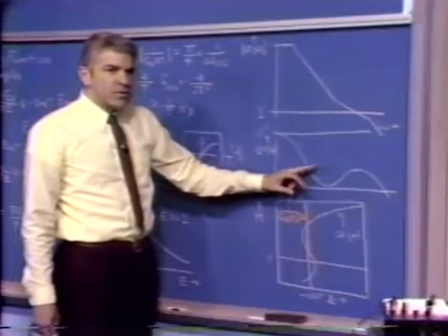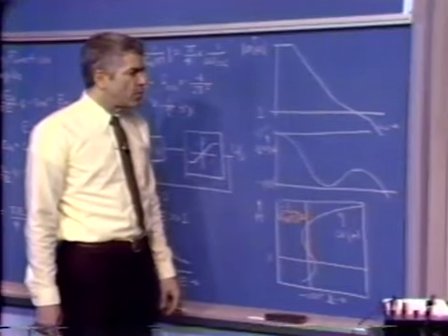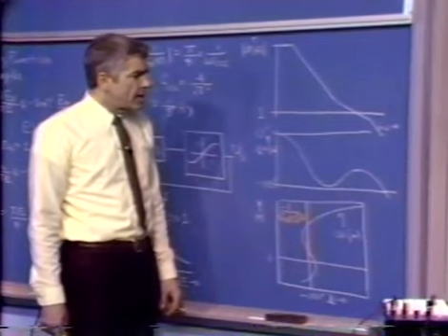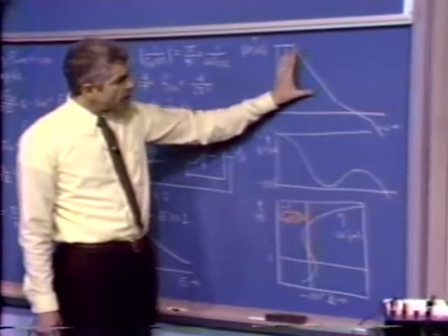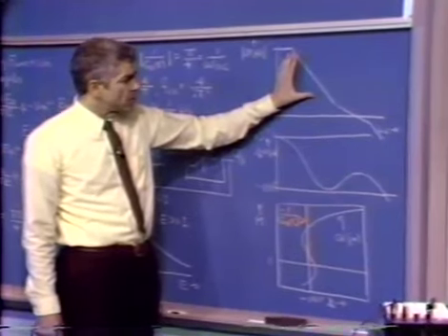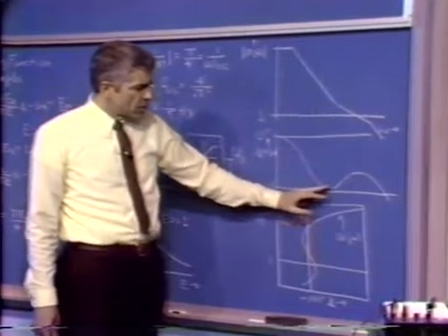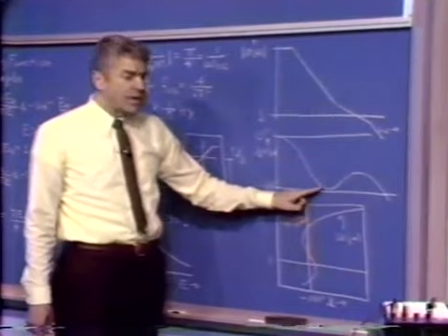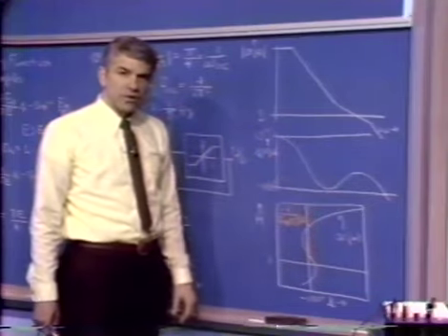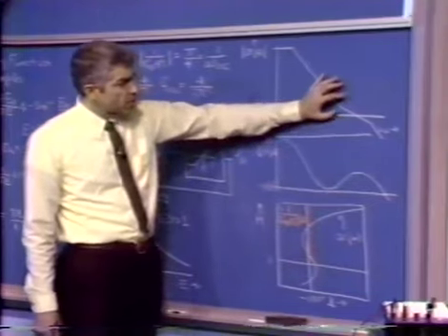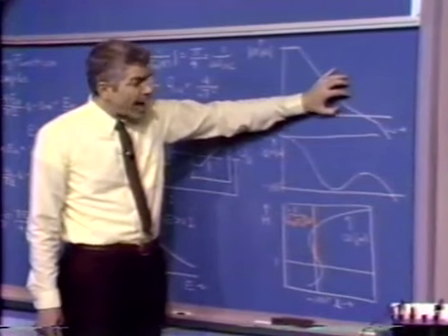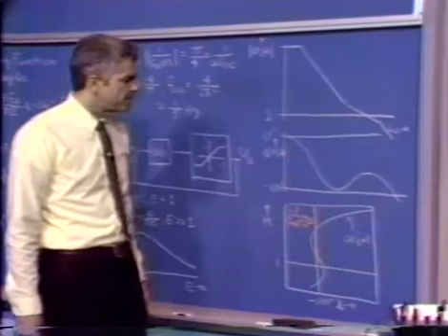We've seen these general sorts of characteristics before in at least two examples that we've looked at. One was lag compensation, where we ended up with a 1 over s squared region in the loop transmission of our system. And again, you recall that there was a dip in the phase. It wasn't quite this pronounced, but it did dip down and then recover somewhat in the vicinity of crossover because we had taken the precaution of locating the 0 associated with the lag network back fairly far from crossover.